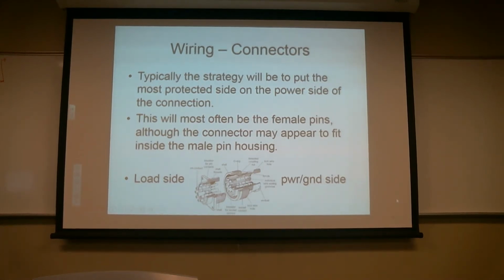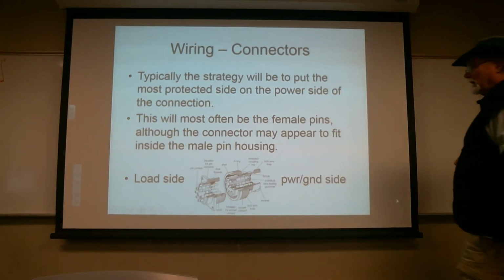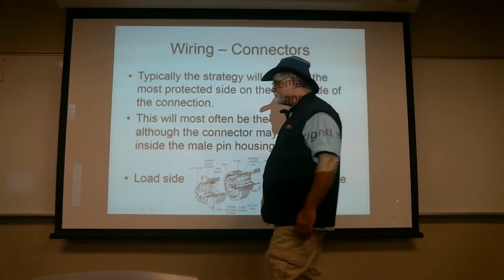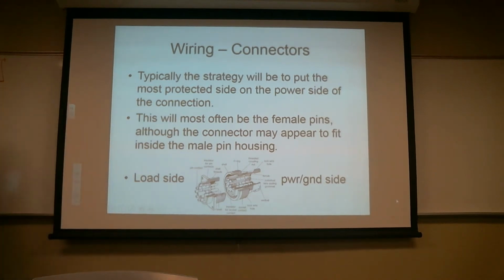Now that's not universal. Like that big fat wire we saw in the initial picture, I could have a big huge connector where, in a number of cases, my load is on this side and power source is on that side, and then in other connections it's reversed. So this isn't a universal mandated strategy in Part 23 or anything like that, but it's generally a good philosophy, and as such, manufacturers often follow that. Okay, hopefully that makes a lot of sense.